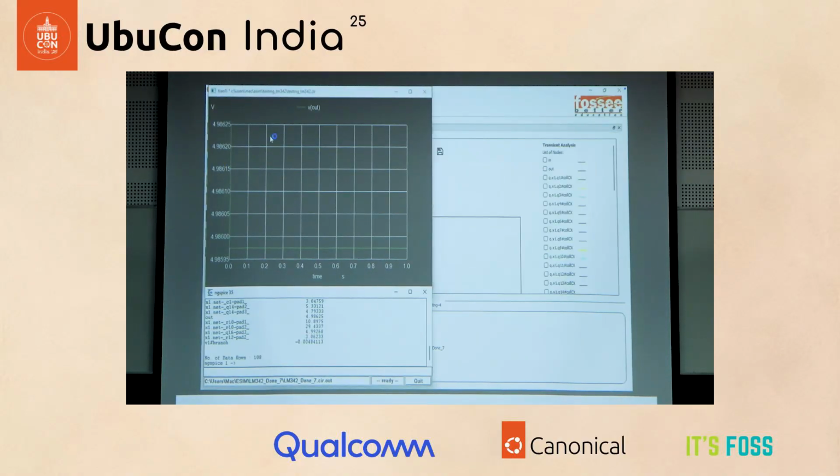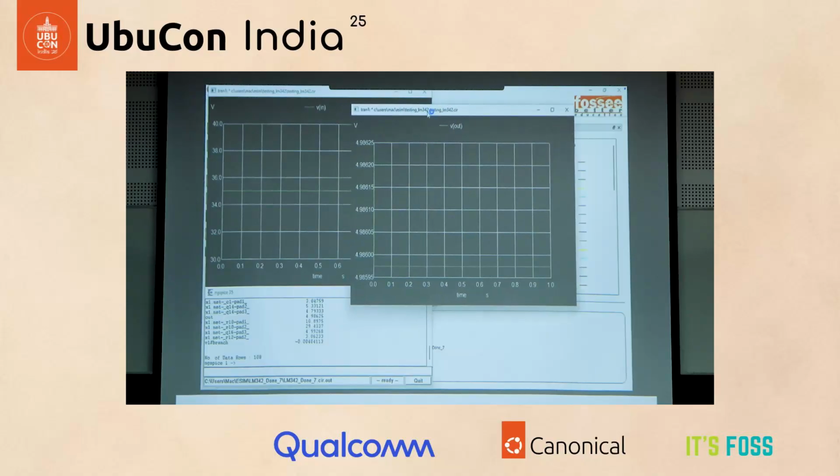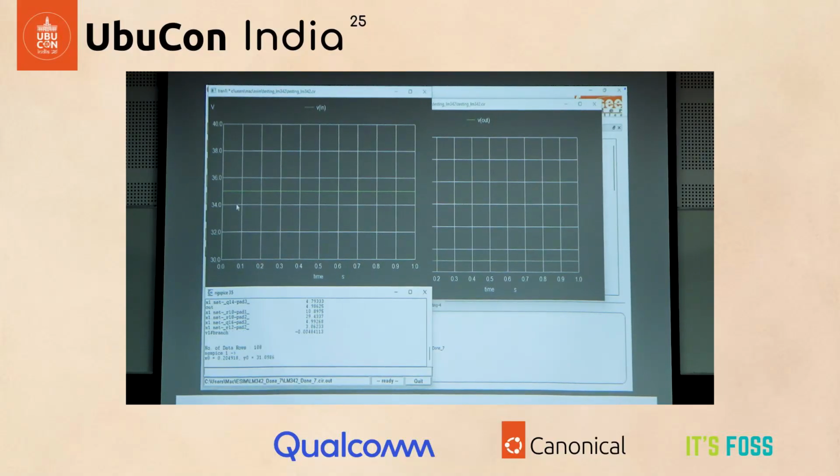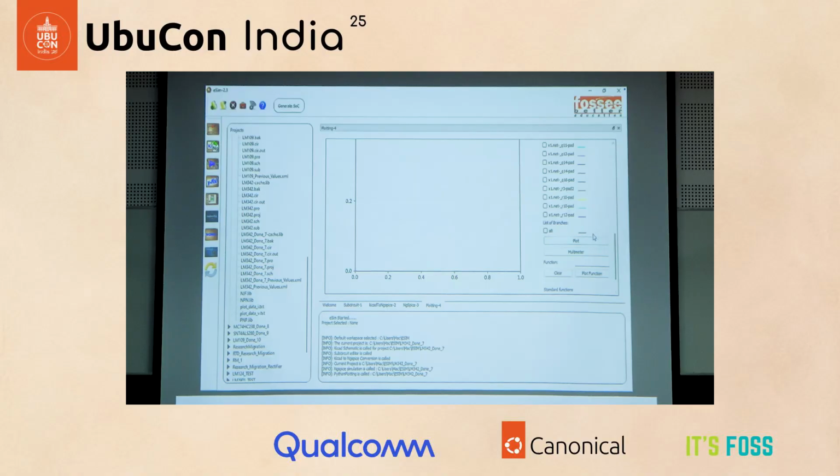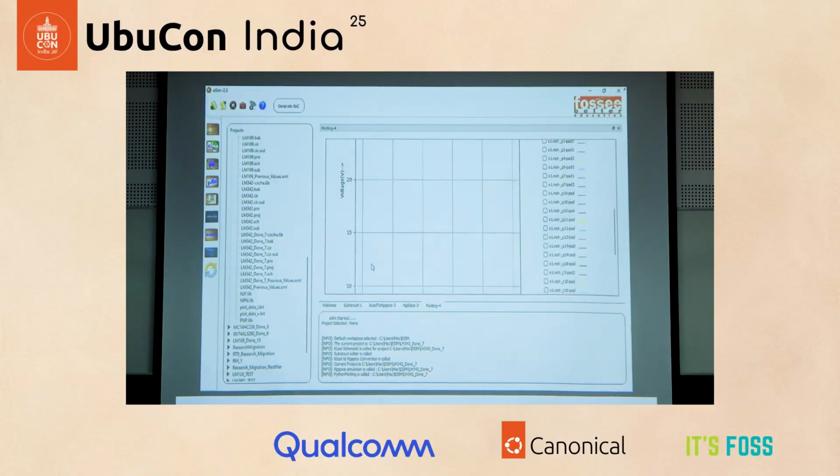Once it's there, when you click on simulation, it shows the Ngspice plots and the Python plots at the same time. These are the Python plots, and this is marking the input and output. After that, click on the plot, so you can see what's actually happening. It's a voltage regulator that I built.